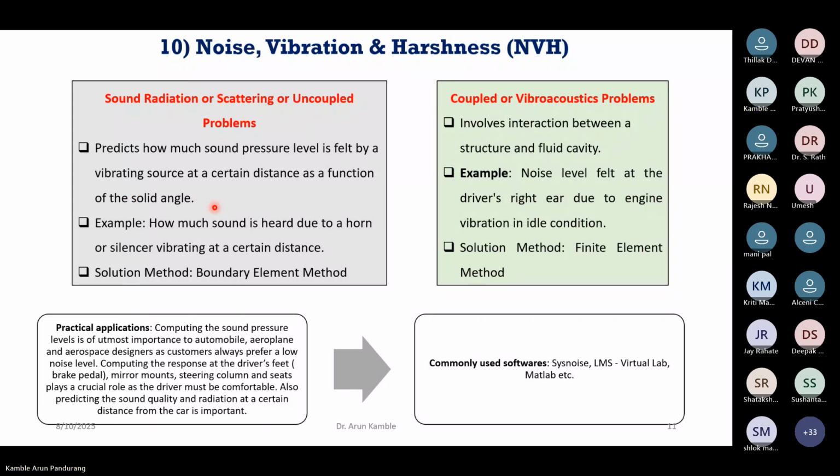scattering problems. So here the solution method is boundary element methods, because as the name suggests, it only considers the boundary of the problem. And the second one is the coupled or vibroacoustic problems. So the examples are we can analyze the noise level felt at the driver's ear due to the engine vibrations in idle conditions. So in this case, we can use the finite element methods.